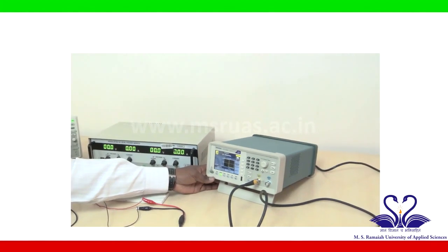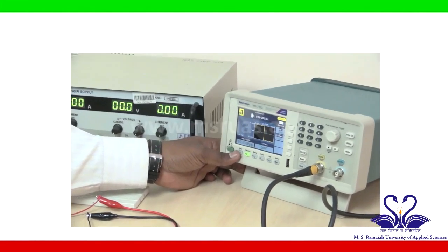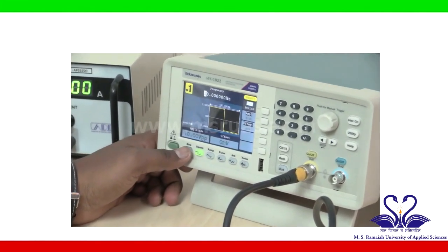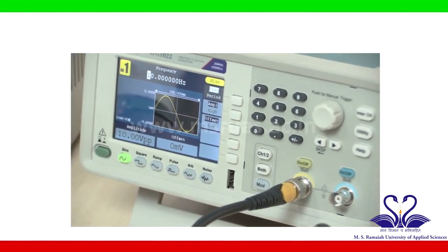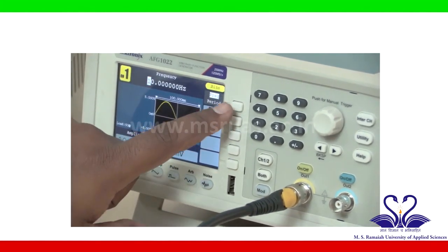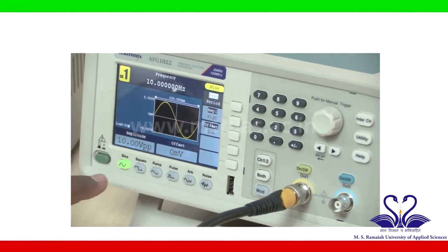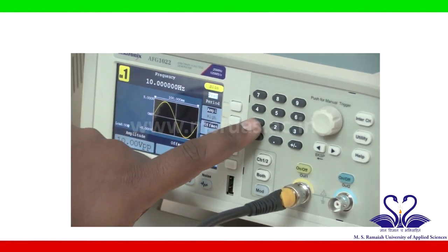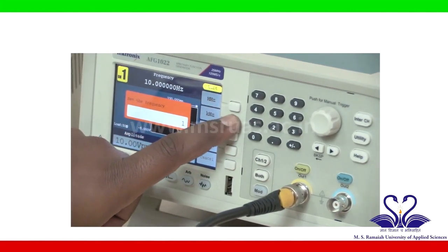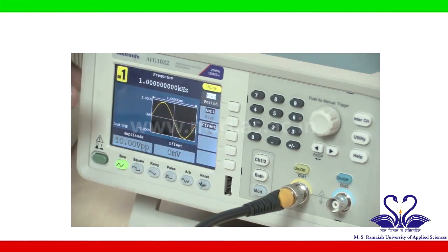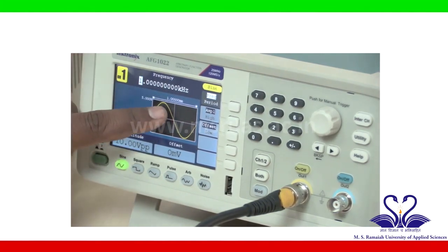This is the input voltage which is given to the circuit. We need the input as a sine wave for this circuit. Click on the sine button, and we need a sine wave of 1 kilohertz frequency. Here we can select the frequency of the signal. Click on this button, then set 1 kilohertz: press 1, then it will ask for the units. We need kilohertz, so press kilohertz. Now, we have set the frequency of the input voltage as 1 kilohertz, and it is a sine wave.